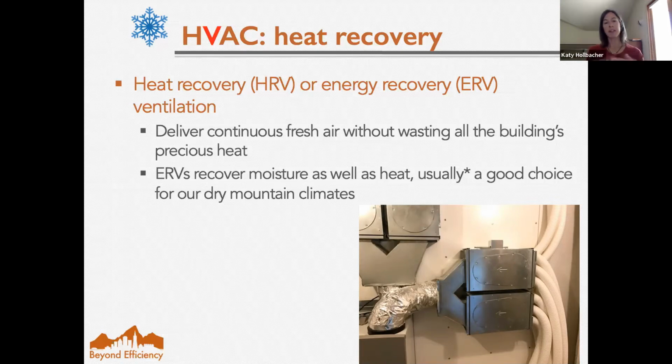The heat recovery ventilator will pass the airflows through heat transfer plates or technologies, depending on the system, but without actually mixing the air streams. It's just basic counterflow or cross flow physics. And it can recover, with a decent unit, 80% or 85% of that heat.